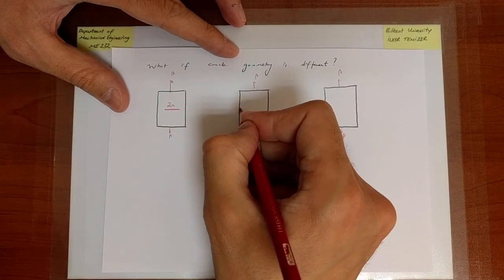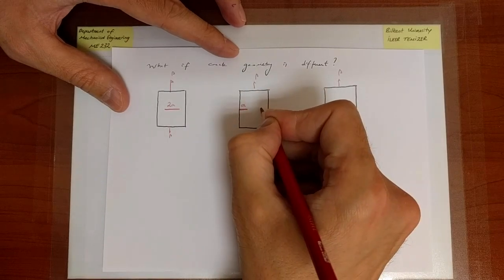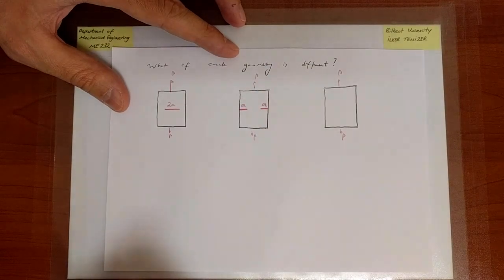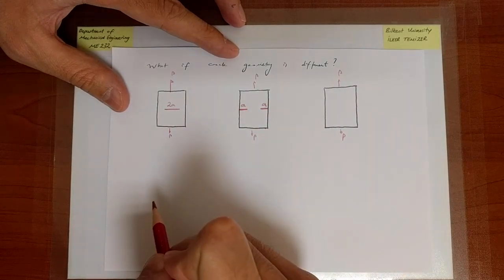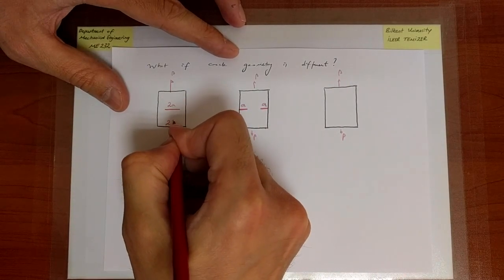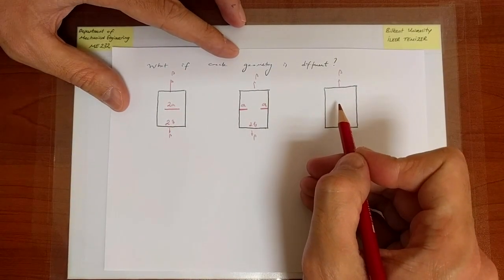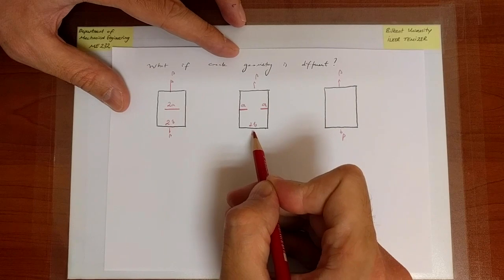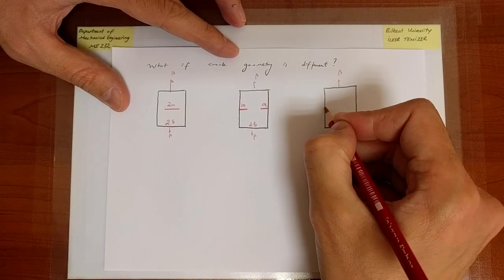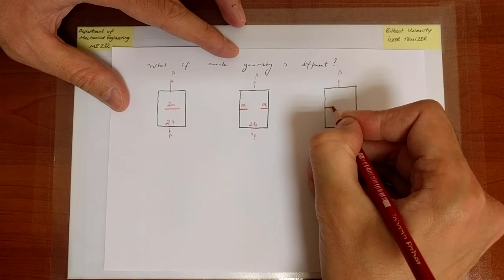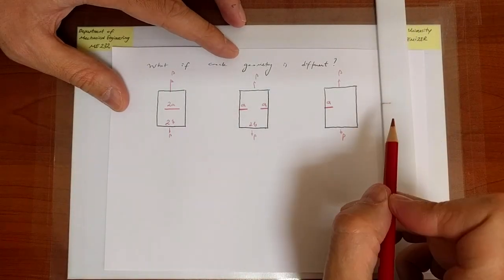In the second case, I'm going to put a crack on the left of width a, on the right also of width a. Okay, so still overall width is 2a, but half of it is on the left, half of it is on the right. Here the width is 2b of the plate, here it's also 2b. In this case, we're going to think as though we take a cut through the plate, and we are going to imagine as though there is a crack only on one side of width a, similar exactly to that scenario.